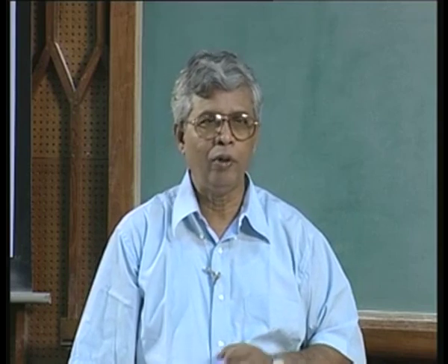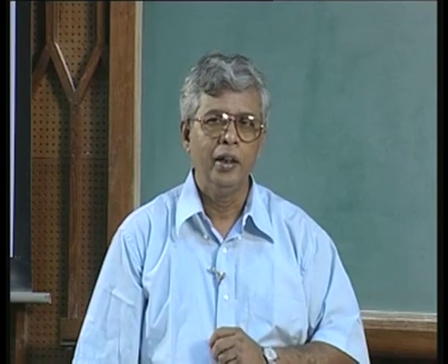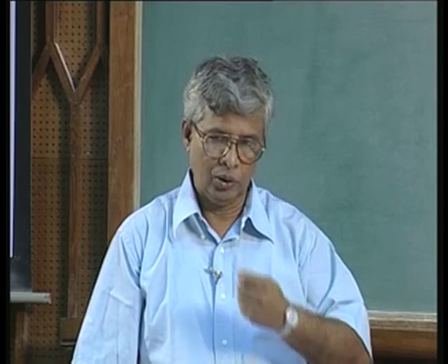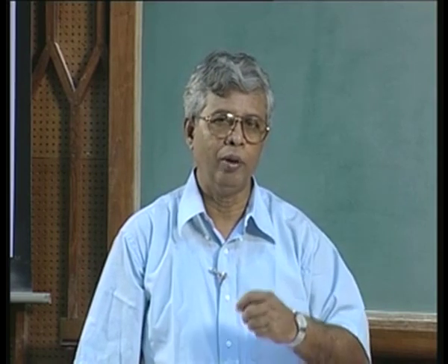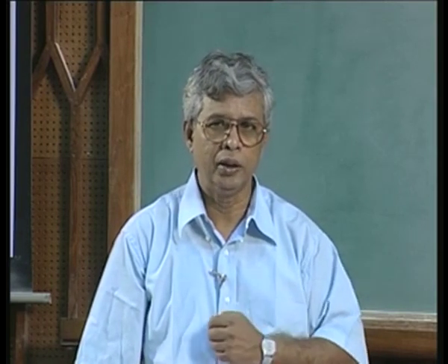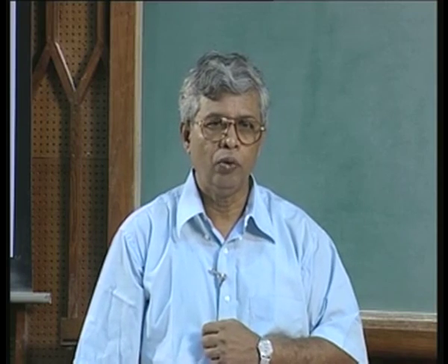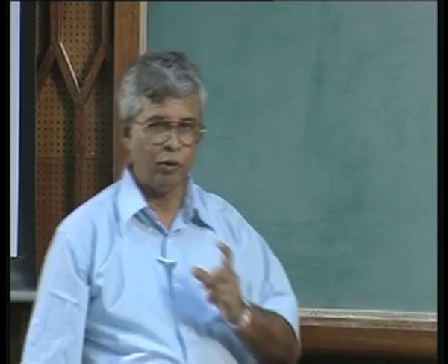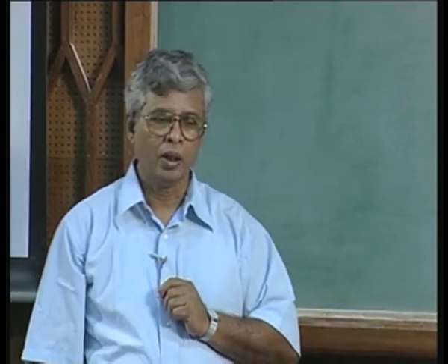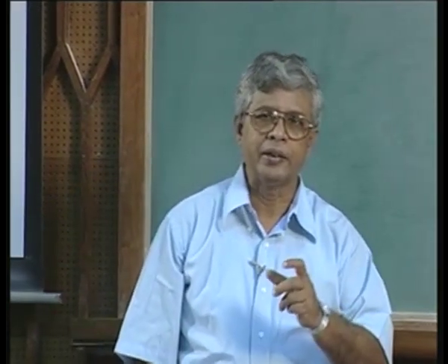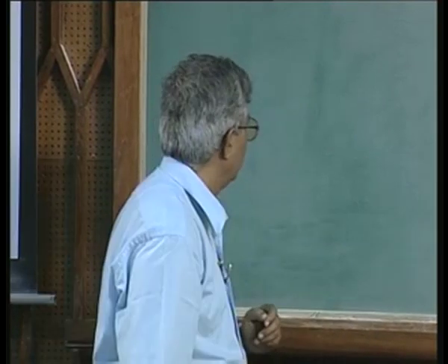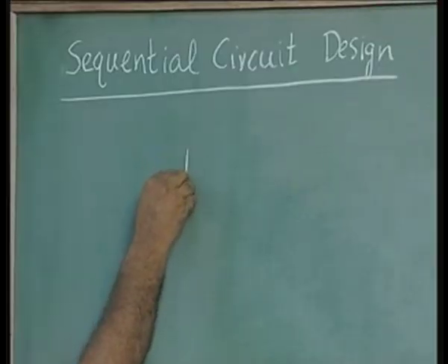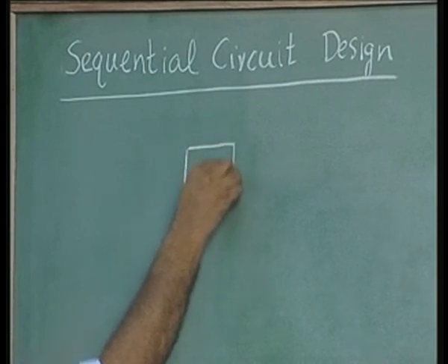On the other hand, if you have only one full adder and you want to add 2 numbers which are more than 1 bit, multi-bit numbers, we go in for a technique called serial adders. That means, the same full adder will be used repeatedly for adding different bits of A and B. So, this is how the 1 bit full adder is going to look like.